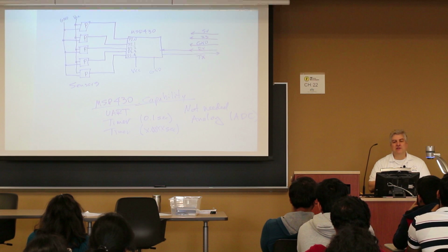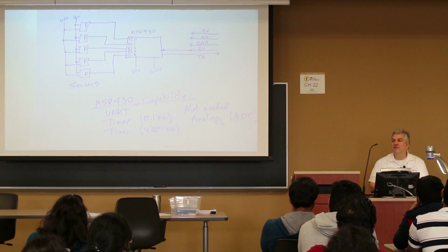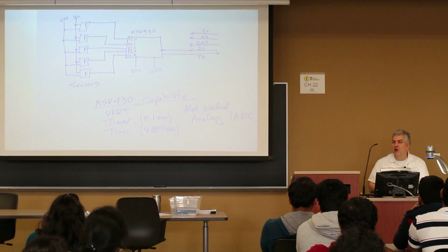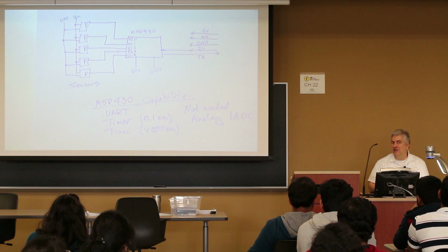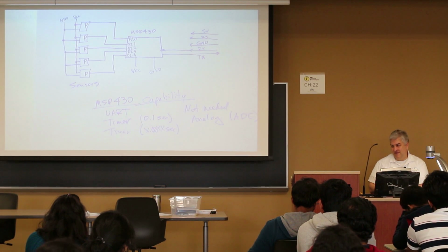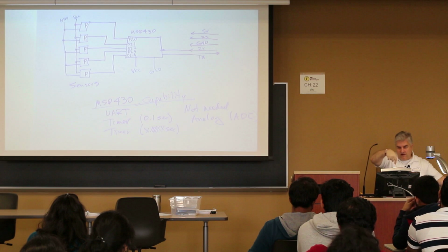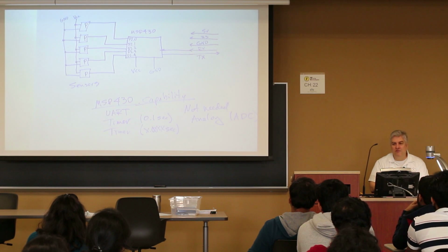Okay, think about this. They're in different directions, that's right. What happens if you send all 5 at the same time? And then what happens? Well, what if it hits something, right? It'll come back and it will be measured by just one sensor, or might it be measured by several? It's possible it might be measured by several, depending on the shape of what it reflects off of. So with an ultrasound, you have to say ping, ping, ping, ping, ping. And do you have enough time to do that? It's part of the problem that you have to solve.